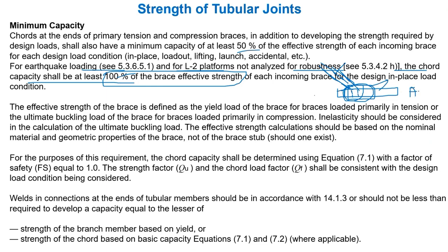But at that time, we will be increasing the allowable stress with a 70% increase instead of 1.33 for the extreme cases. But we will be carrying 100% of the brace load to check. This is what the code requires.